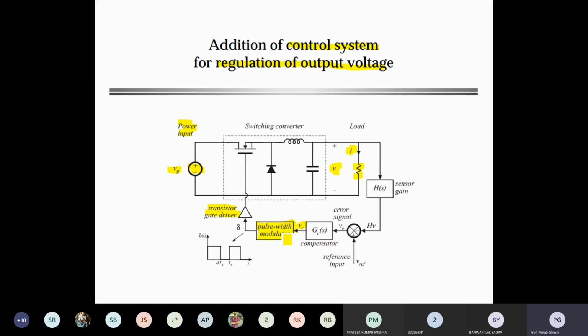Without changing your output voltage, you can say that the load regulation is the percentage change in the steady state output voltage when the load current is increased from 0 to fully rated current. So you are changing the load current from 0 to maximum, and checking how much the range can go, or more commonly from 50% to 100%.